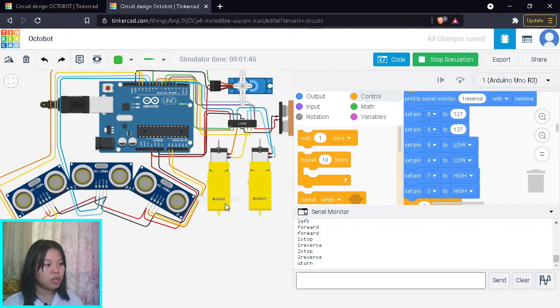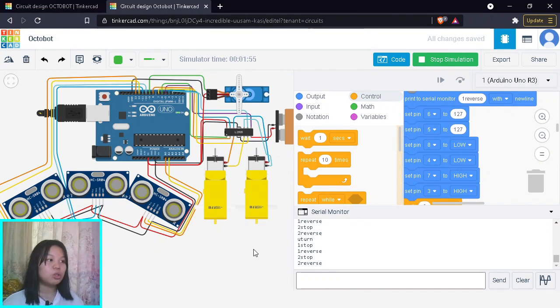For the U-turn, we see 183 RPM, positive RPM moving forward at greater speed, and this is negative 130 plus RPM, so it's moving in reverse at a lower speed. This one was moving forward and this one is going in reverse, so we get the U-turn position. That is all our 5 scenarios. Hope you get it done, and thank you for watching.